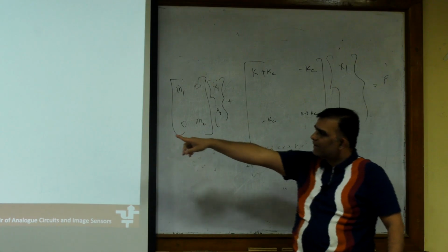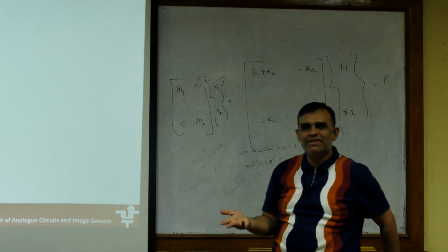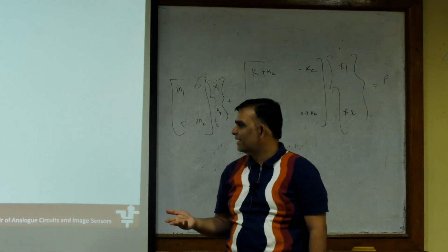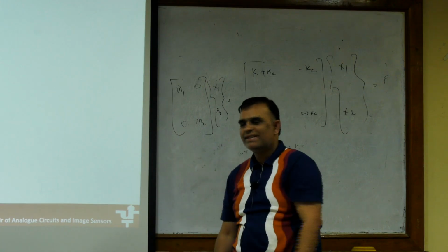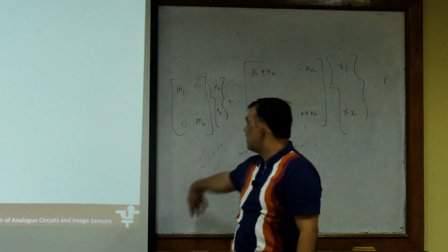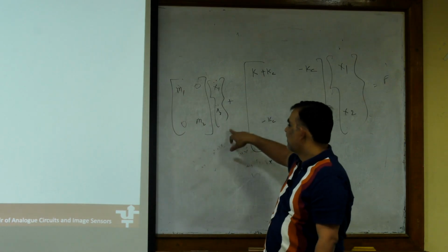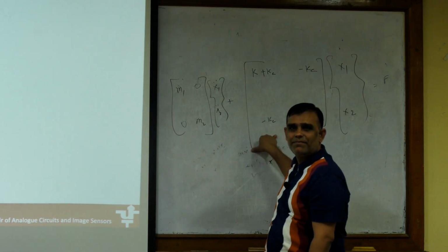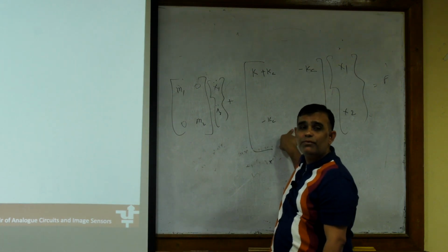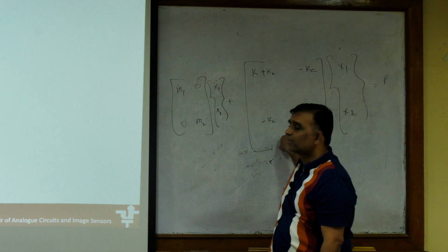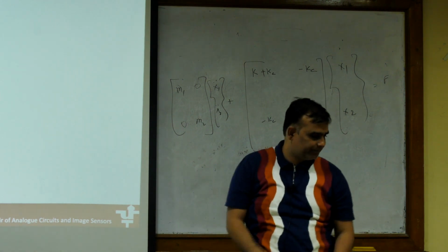Now, if you remember, that equation looks like the starting situation of the eigenvalue relationship which we teach to our students, right? And I can write this as, you can take m as m half, or even you can normalize the whole m to become 1. We can take all masses to be 1. This becomes the eigenvalue relationship. It's the eigenvalue of this matrix which then tells me at what frequency my system will move, and the eigenvector which tells me how much they will move by. Okay?